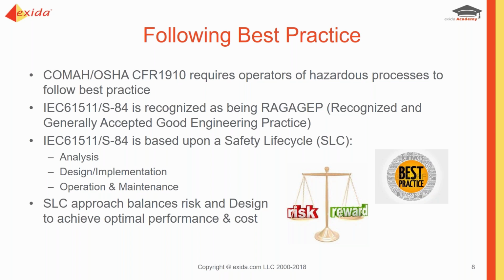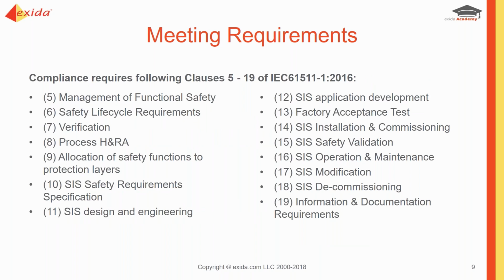So the life cycle then requires us, from the IEC 61511 point of view, to be compliant with the following clauses. So the first one is management of functional safety. So this really is, how are we going to manage doing or achieving functional safety throughout the safety life cycle? And this is very important.